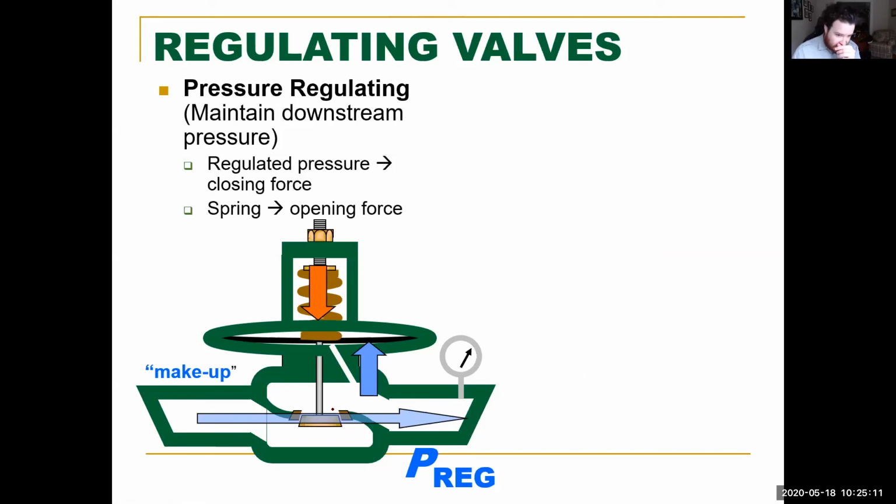Is as this fluid goes through, this pressure down here, if it overcomes the spring force, it will close the valve because it will push up on that baffle.